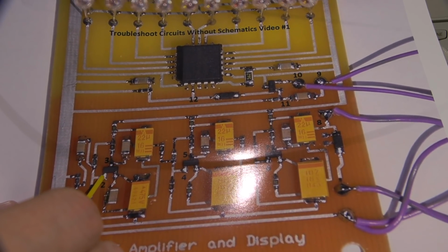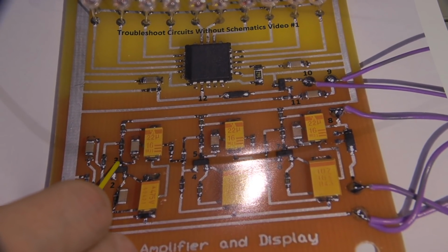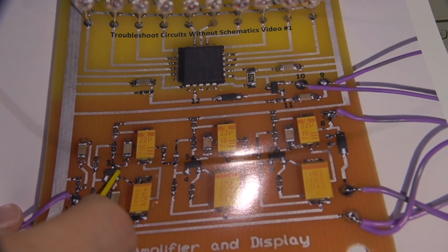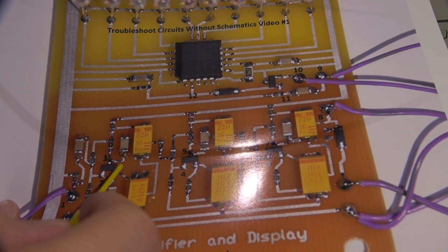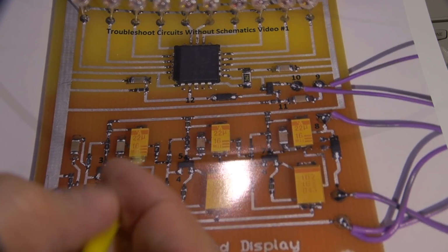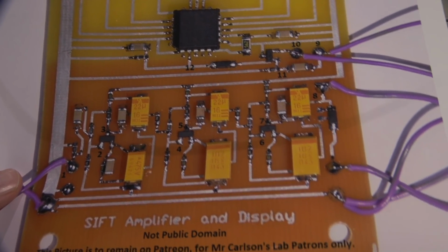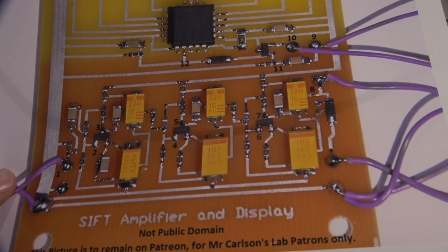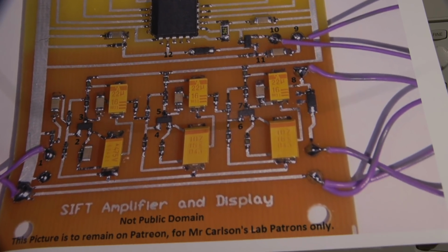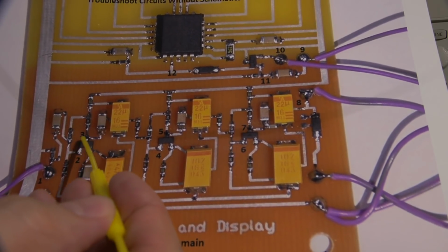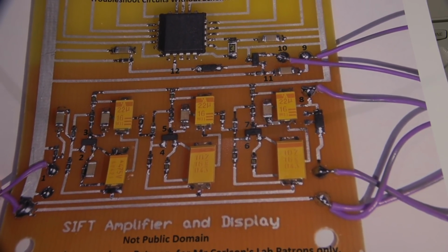If there is an amplitude difference, so if the amplitude is bigger on 3, it really is that simple. We know the thing's amplifying. And then, you know, on to the next stage. So if we had a dead amplifier or something like that, we would know this stage is working. And the same thing is for vacuum tubes as well. Grid to plate, grid to plate, grid to plate, right? So this would be grid and plate on a vacuum tube, right?